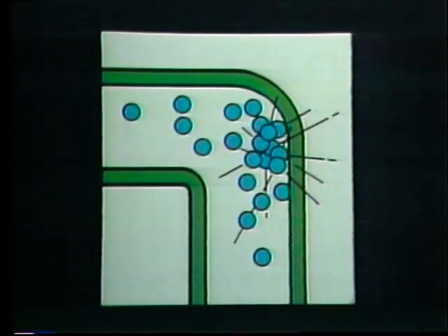Some of you may be responsible for actually making new pipe installations. So here are a couple of points with which you should be familiar. First off, when you're laying out a distribution system, try to keep the number of fittings you use to a minimum. Remember back in Lesson 3 we talked about friction and changing fluid direction?